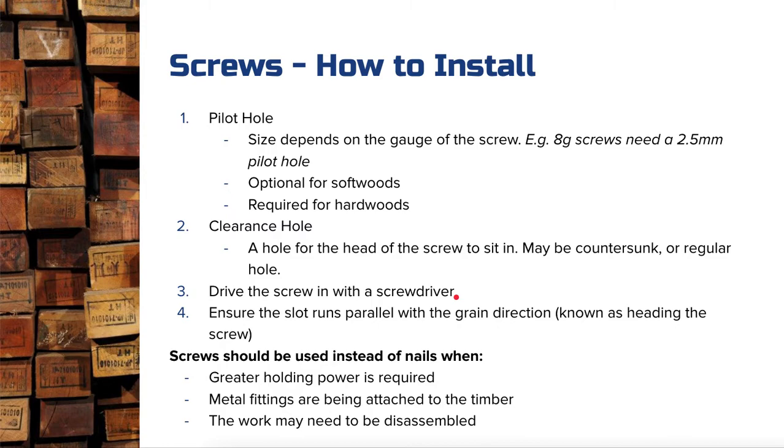The last thing that we talked about with screws, this is something most people don't know, is this process called heading the screws. So if you have a slotted head, so not a Phillips head, but a slotted head, one single slot, you use a flat-headed screwdriver, then you would actually turn the screw so that the slot is parallel with the grain direction on your timber to head the screw. It actually makes it look just a little bit neater. It's a little trick of the trade, not many people know about it. If you've got a Phillips head screw, you would turn it as well, trying to get it exactly parallel and perpendicular with the grain, just so it's not sitting at that off parallel direction.